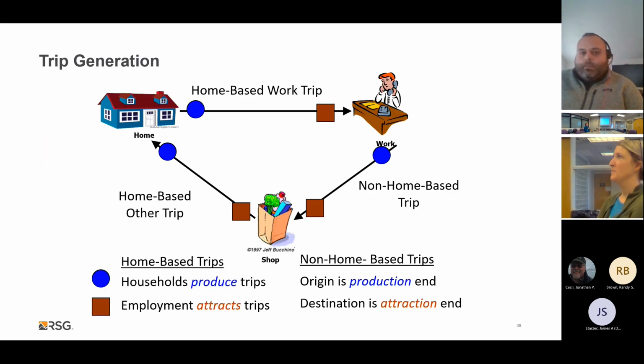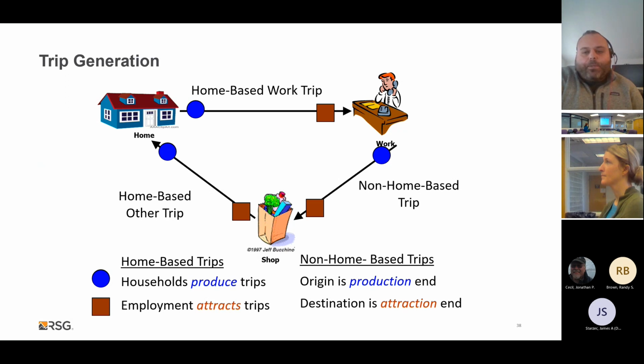And that's basically based on income level and destination choices, or whether they're going to work or groceries. Yeah, trip generation is going to be based off of the purpose. In the AMATS model, for example, it's based off purpose and the income categorization. So there are different trip generation rates for each of those. There's a home-based work for low income, there's a home-based work for medium low, and so on and so forth for every single purpose that's developed in the model. And that creates the rates for the total number of trips that are being taken.